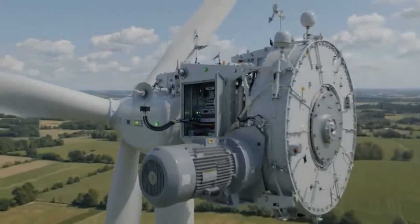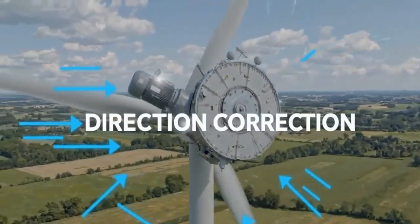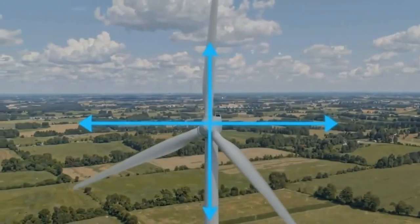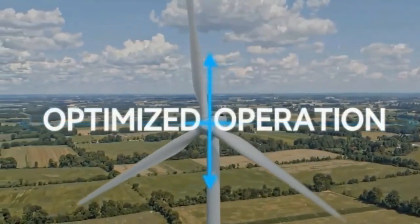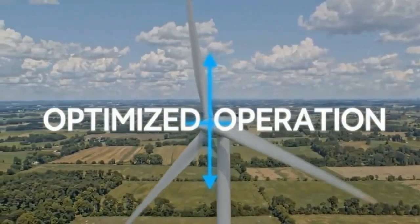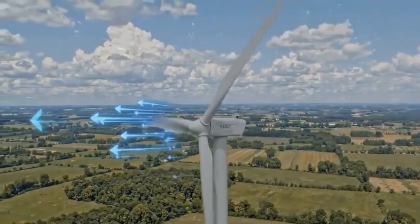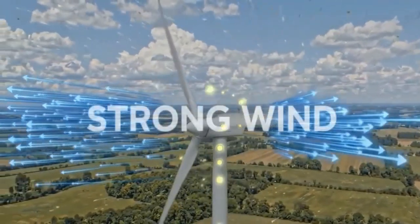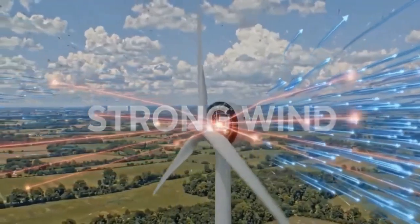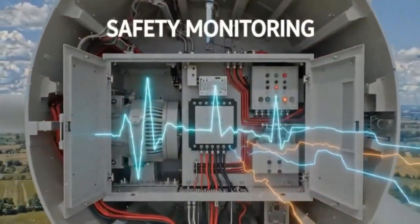The yaw system forms a control loop: sensors measure wind, the controller calculates, and motors turn the nacelle. Each yaw correction is slow and heavy because the nacelle and rotor assembly has enormous mass. When yaw and pitch work together, the turbine can maintain efficiency as wind direction and strength change. But if the wind grows too strong, the system must shift from optimization into monitoring and protection.